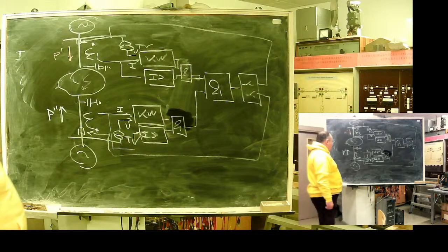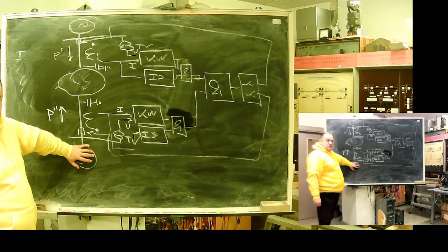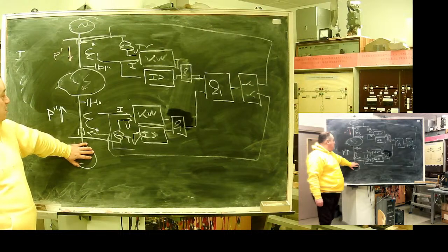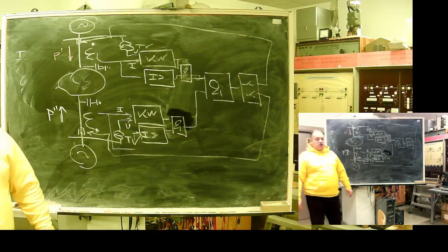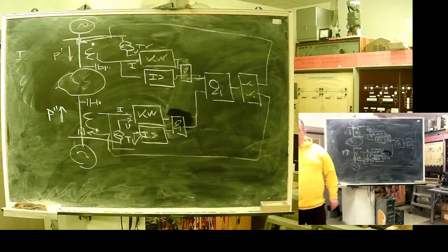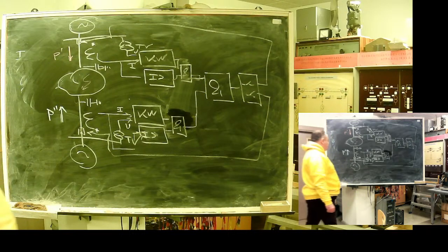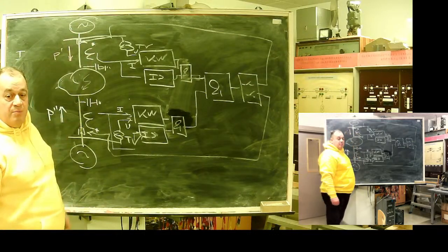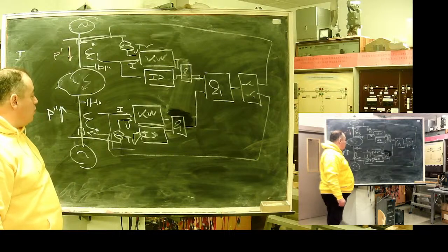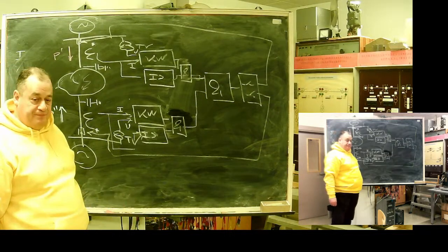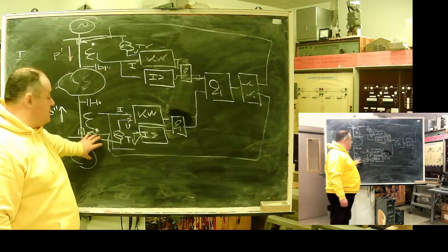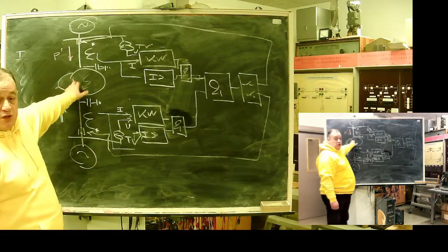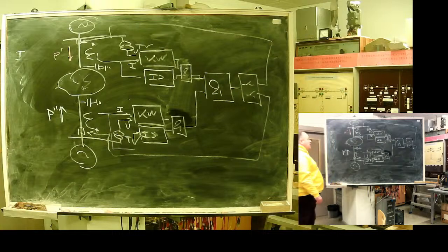But if we are in a situation where this source is not available, protection will fail, because any source may be disconnected. Protection will fail because there will be no current to operate at this site in case of an internal fault. So this kind of protection operates instantly.